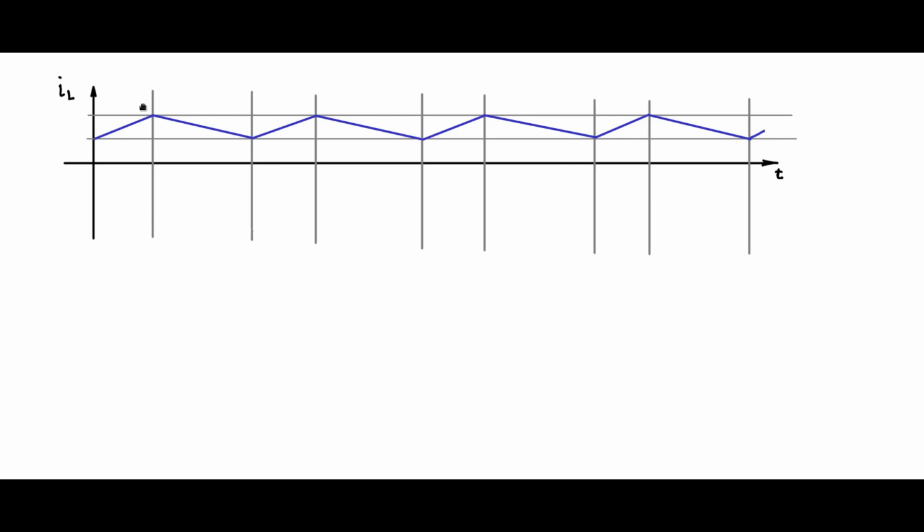Now let us see what happens if there is a disturbance. Now I will introduce a disturbance here. I'll just offset it. Disturbance could have occurred due to any number of reasons. Let's say if this disturbance occurs, the inductor current will start on from here. It's an integrator. It will start on from here with the same slope, V in minus VB divided by L. So it will go parallel to this line.